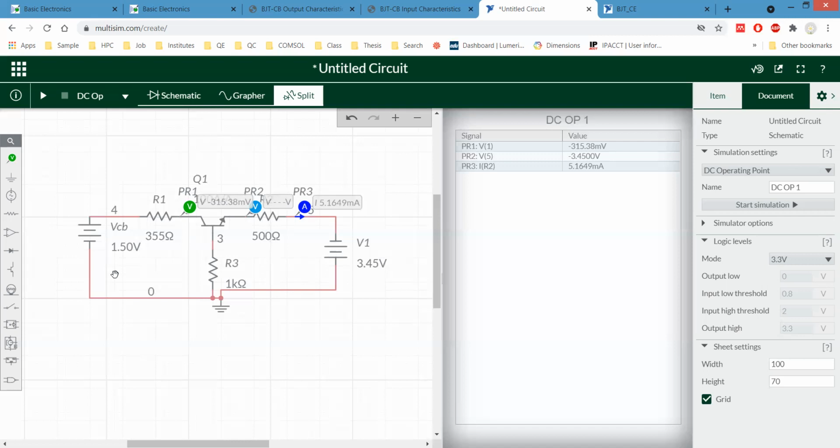And this is also one of the good examples that we can use a transistor as a switch. If you just flip the bias across this, and let's say we keep the collector base junction bias fixed, and we just flip the bias of the base emitter junction, then depending on that you will have a switching condition between the cutoff region and the saturation region.